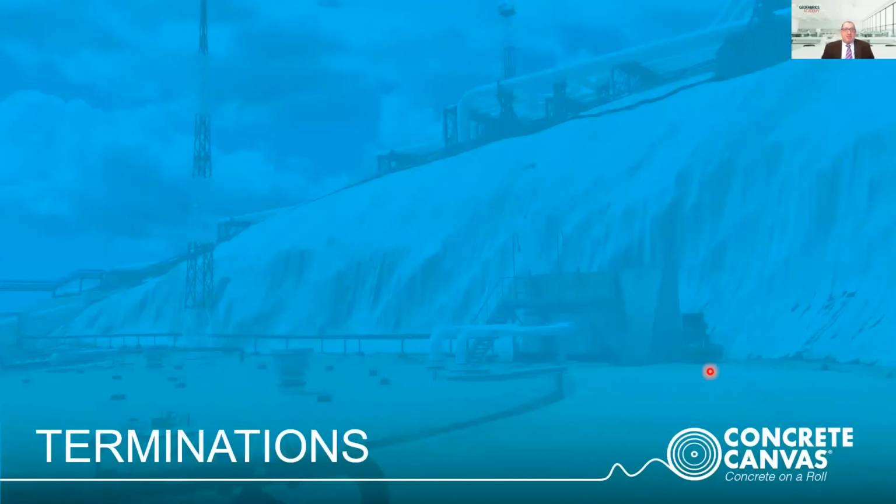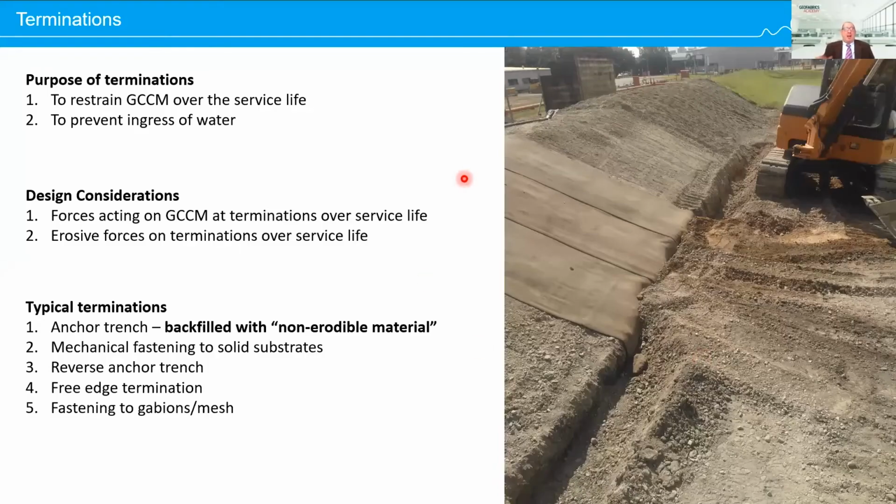Okay, terminations. Now, the purpose of terminations is to restrain the GCCM over the service life. It's to prevent ingress of water underneath the GCCM. The design considerations for GCCMs are we must consider the forces acting on a GCCM at the terminations over the service life. We must consider the erosive forces on terminations over the service life.